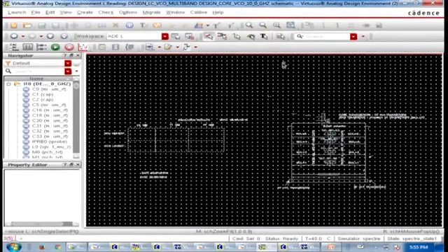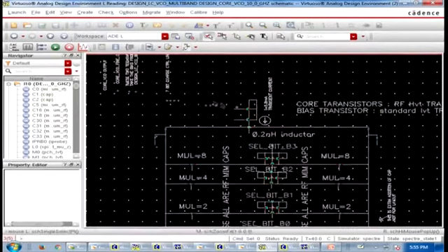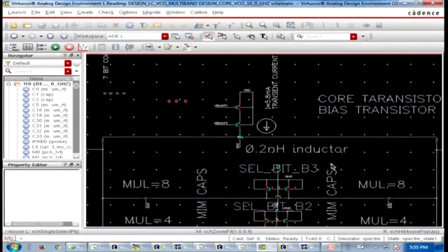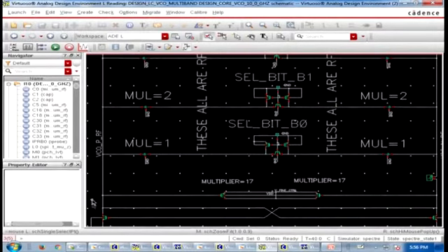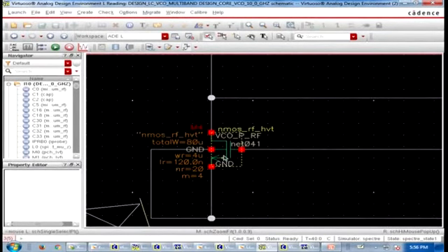Another point is that if you burn more current, you have to have a larger aspect ratio for these two transistors. So their gate capacitance also comes into the picture, which is parallel to the inductance. So again your frequency will come down. So there are multiple dimensions, you cannot go anywhere. If you go there, it will be problematic somewhere else. So this is typically the thing.